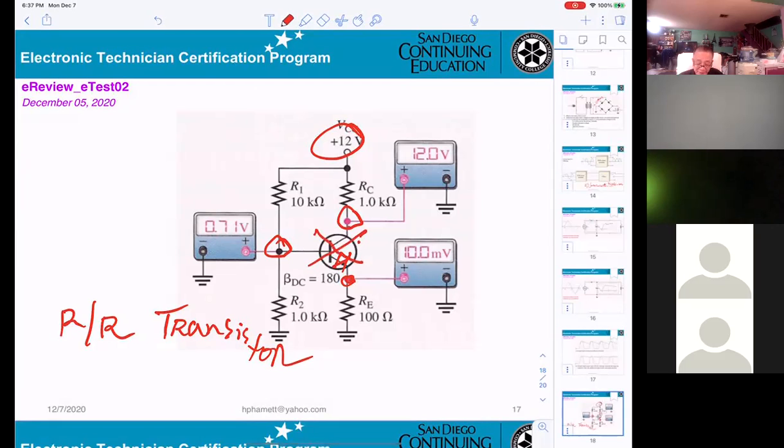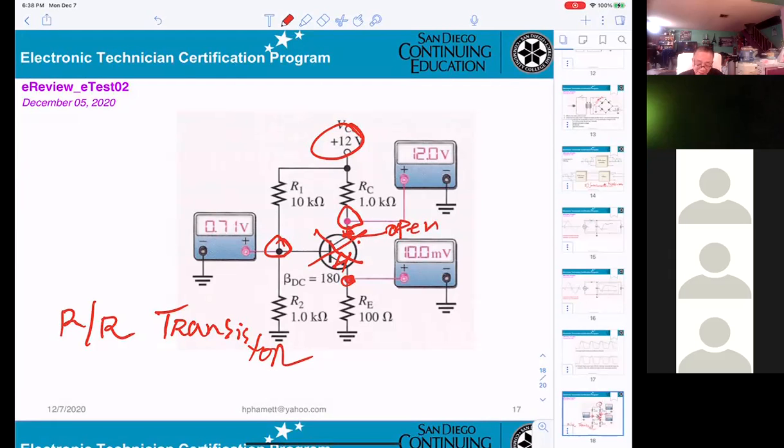So that's why they open, right? They will be open here. It's the diode from base to whatever. Inside the transistor, we don't care. But they're telling me the part to remove and replace is supposed to be the transistor. The transistor is not working, right? So that's why when they measure 12 volt here, they measure 12 volt here. That means the current cannot flow from here down here.